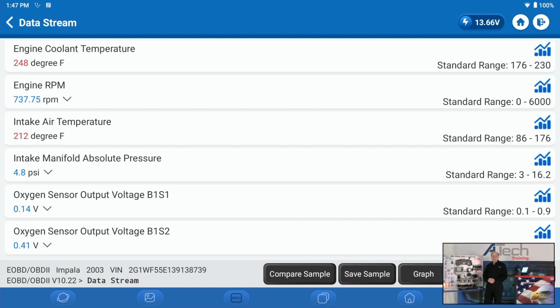You see the RPM start to change a little bit, and we see some temperature changes. Again, the O2 sensor right now is working at idle. Off idle, it has a little bit of a problem. So we're looking at data across. Now, I could graph this, but I wanted you guys all to see this at the same point. All right, so this is the inputs we'd be looking at on the particular car.